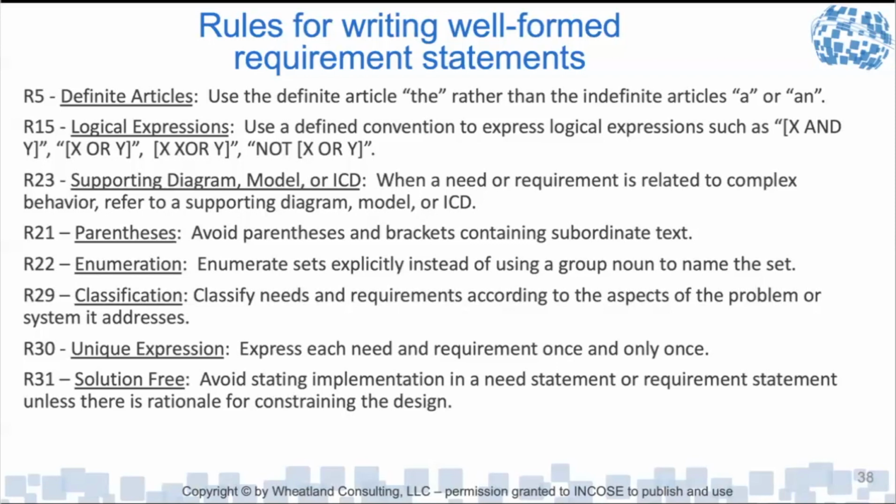I say that as an example because for like the NASA Ares rocket, and then for the launch vehicle that they're developing now, management says, we want you to reuse this engine as is. It turned out that when you did what I've talked about, all the requirements allocated to the engine and all the interfaces that the engine had to have, that off-the-shelf engine turned out to need a whole lot of modifications.